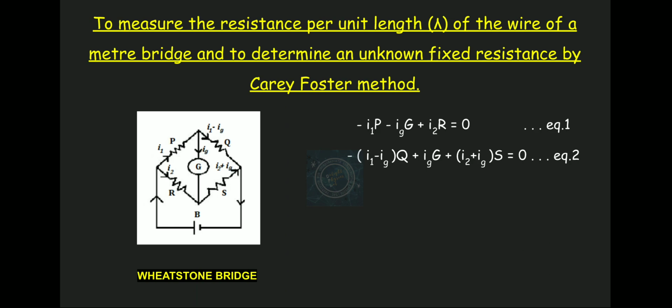And you know the next step, it's obvious. I will equate the galvanometer's current to 0 to find the balanced condition. Because as you know, when the bridge is balanced, the potential difference between the PQ junction and the RS junction is the same, so it's shorted, no current flows.